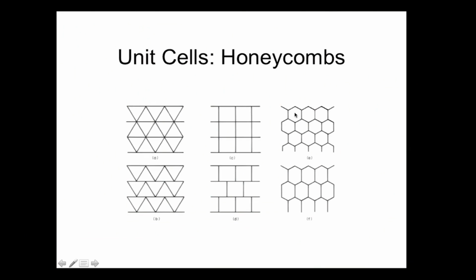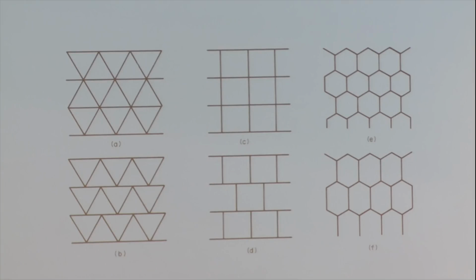So in 2D, the face and the cell is kind of the same thing, right? And then in 2D, a side is equivalent to an edge? It's not quite. If I count up the number of edges, I say 1, 2, 3, 4, 5. But if I say sides of the face, say that's a face or a cell, I would say that had 6 sides, right? So, typically when people say a cell or a face has so many sides, they count up how many all around it.